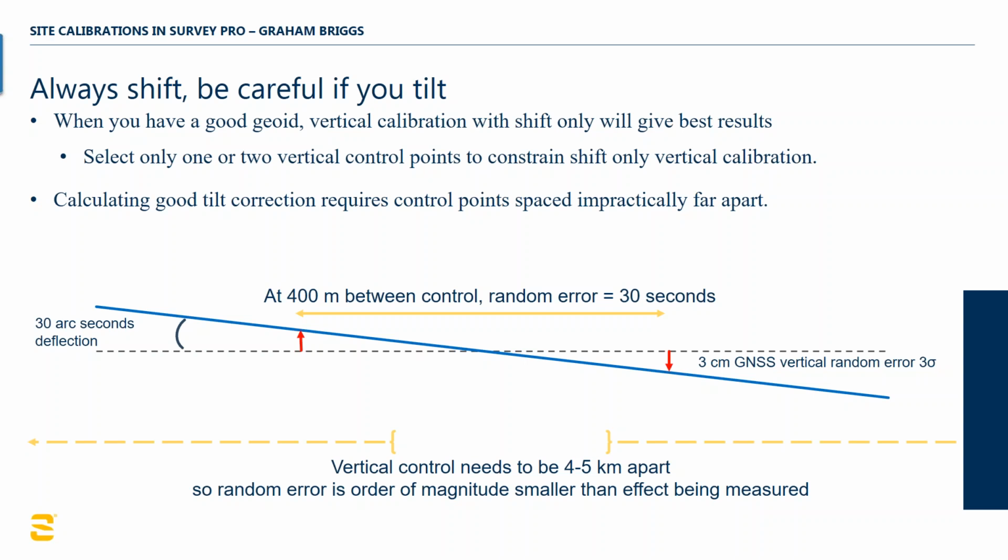People rarely do that. Yet there's sort of a misbelief, in my opinion, that I always want to do a vertical calibration with as many control points as possible. And I don't believe in many cases that's true, especially in the continental US and in Canada, where for 30 years they've been spending copious quantities of our tax dollars doing tremendous science to measure the actual gravity field of the land.